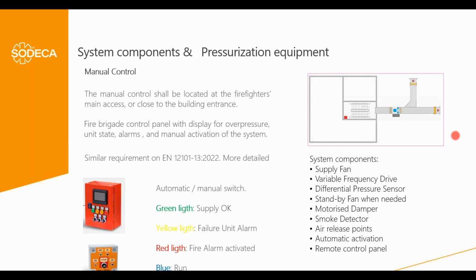This is one of the points of our system: during the first commissioning we press one button on this touchable screen, the system starts blowing air until it achieves the nominal overpressure, and then from this procedure the system learns how it has to be activated the next time to achieve this nominal overpressure very quickly, and to react between the door open and the door closed condition. So this is a self-calibration solution that we include in our system.